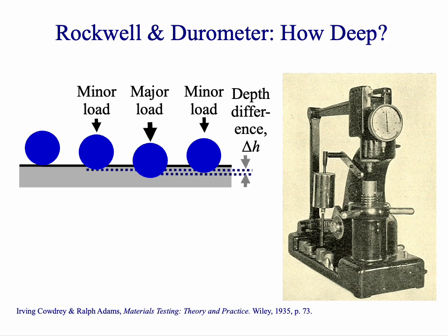Today, we're talking about mechanical properties. The most common mechanical property that we measure is hardness. We typically push a hard indenter into a sample and then measure one of two things: how deep it goes or how wide the resulting indentation is. Stanley P. Rockwell worked at a ball bearing manufacturer, and he needed a good way to measure the hardness of bearing races. The indentations with a Brinell test were too big, so he developed a brand new testing machine.